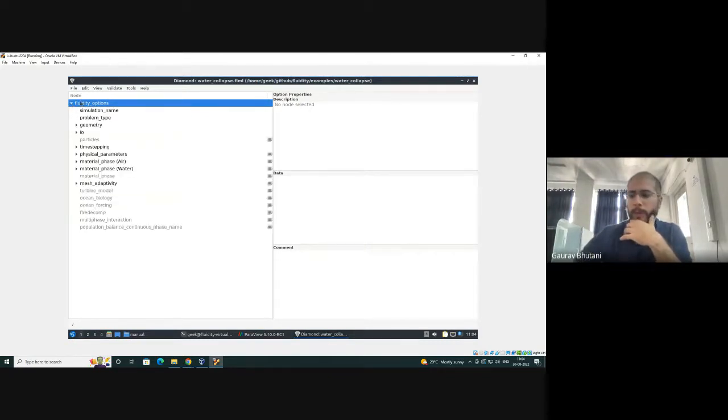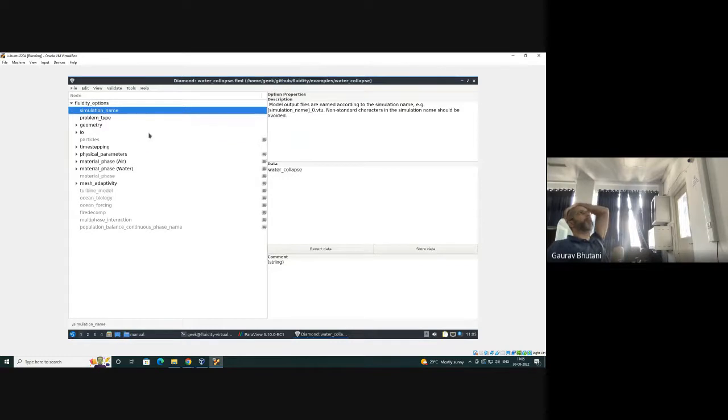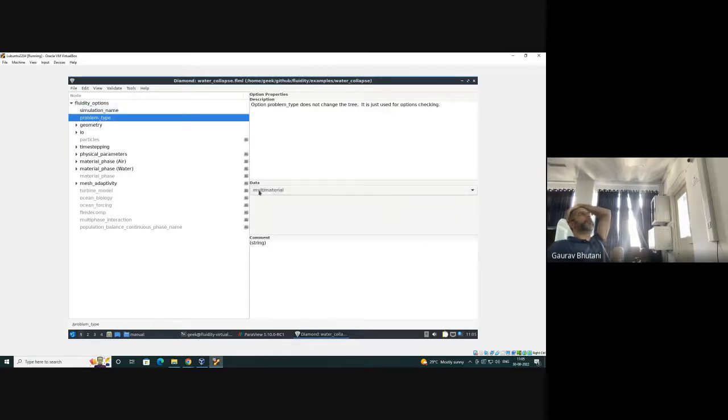Now I want you to follow this and look at the options available here. This will have all the options. The first one is simulation name. Here the data portion is where you can enter information. The name is water_collapse. Everything that gets created will have water_collapse followed by something. The problem is multi-material. I told you it's a multi-material type. It's using the volume of fluid method.